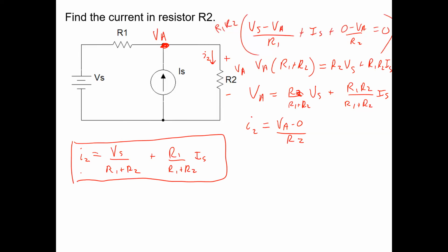Well, Va is a node voltage. And what that node voltage means is if you hook up a voltmeter to that node, as you found in the lab yesterday, and you hook up the common port and the V here, you're going to read Va on your display. That's the potential difference between the top node and the reference node at the bottom, which we're calling 0. So the potential drop from this node to here is Va volts. And that happens to be the same potential drop across the R2 resistor. And so Ohm's law will tell you that I2 equals Va over R2. This is Ohm's law.